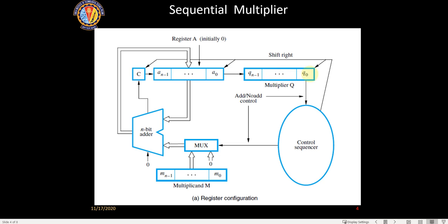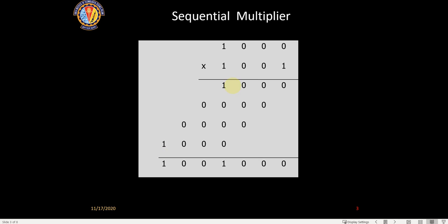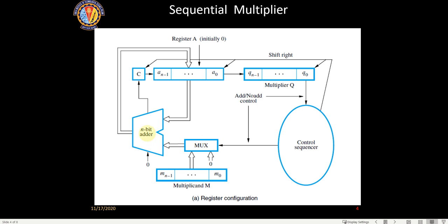Yes. Okay, now in the next positive edge, this 0 is available here the second time, so it will sense a 0, so it will add a 0 here. That means I have shifted this. Now in the next step I am going to add a 0, because it has sensed a 0 here. So this will have the previous data itself, which is not going to change, because I am adding a 0 to the accumulator. So in the next load condition the same data will get loaded here, it will not make any change.